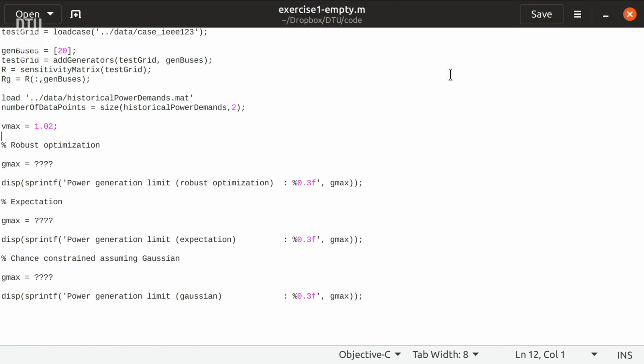Sorry, can I ask? We have gotten a lot of issues. For some reason, when we try and run, we weren't really sure how to create the post-install file. So we just basically created a new file. No, you have to remove this post-install one. Yeah, that's unfortunately the problem. Go to environment, and then scroll down, there is edit post-install file. This will create one, but with higher privileges. So now this post-install one can be run. You copy all the text from the other one in there. Like this. And now this should be fine.